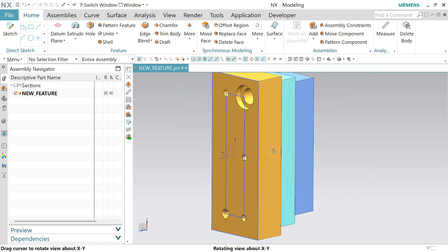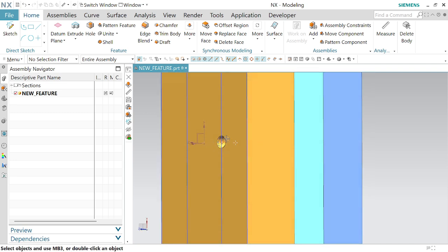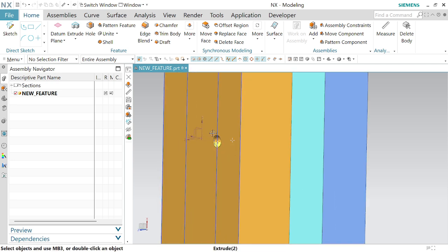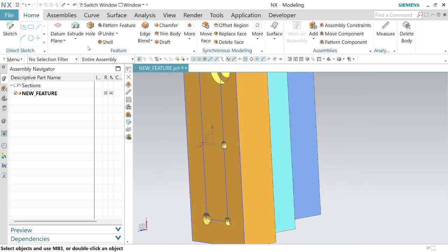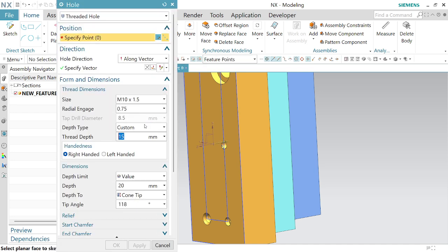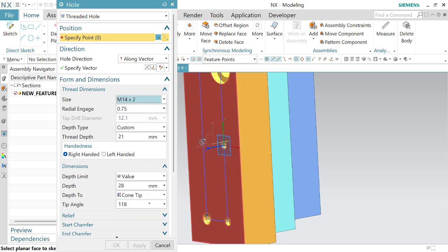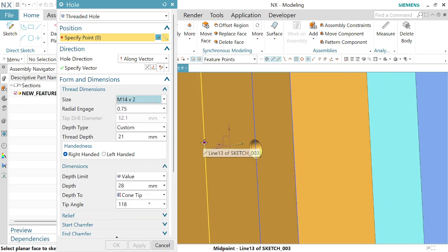So later on the operator will create the M10 threads over there. So it creates the minor diameter. You don't need to remember how big a drill bit we have to use for M10. You just have to select from the chart and put it on your 3D data.